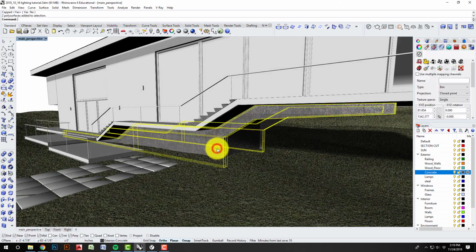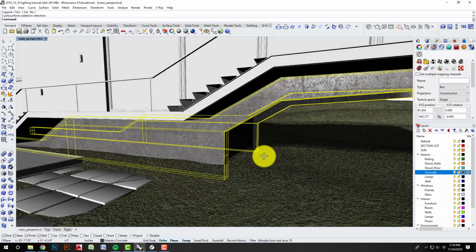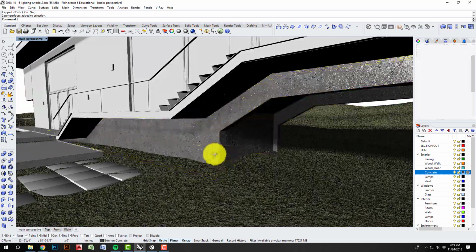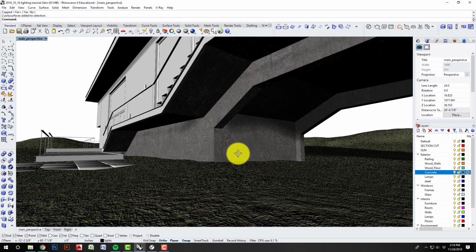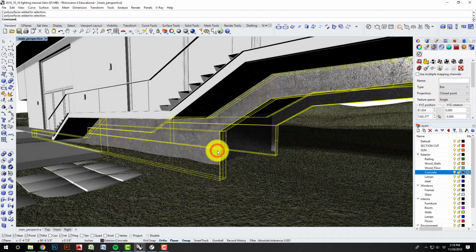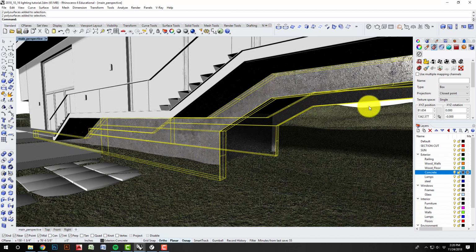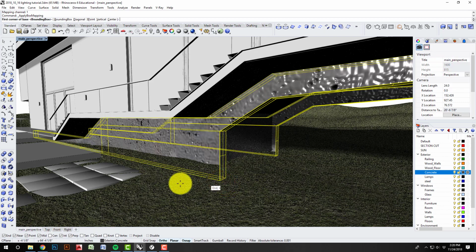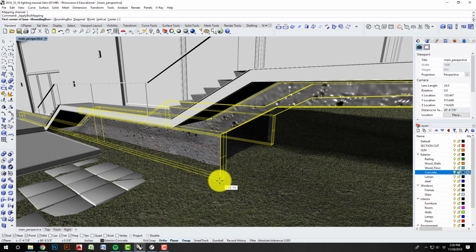But again, I want to make sure it's at the right scale. There was a previous scale left over in this model. So to make sure everything's working together, I'll select one surface here and delete the mapping. Now you can see the default in here. And I'll apply a box mapping to my one surface. For this one, I'll snap to a corner of the piece I'm working on. So again, 2 meters is about 6 feet, we'll say.